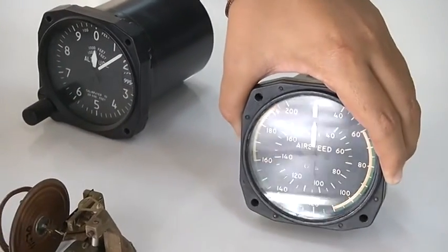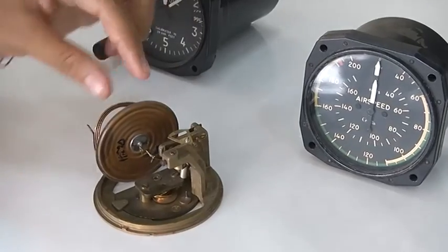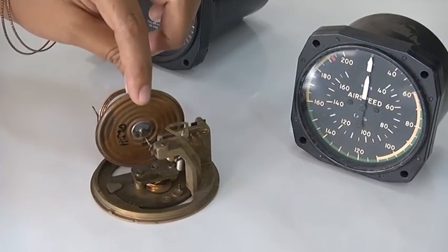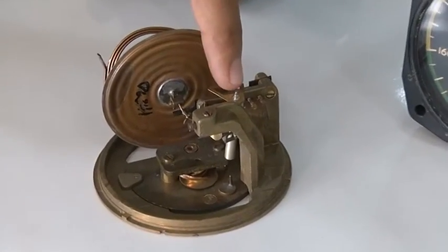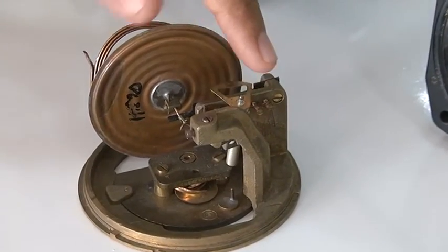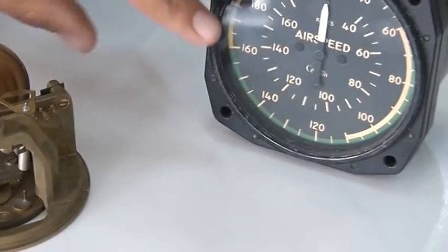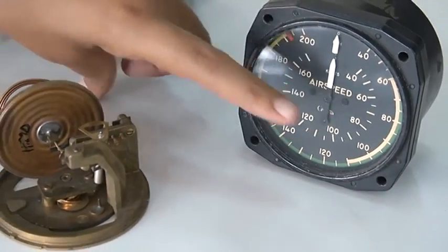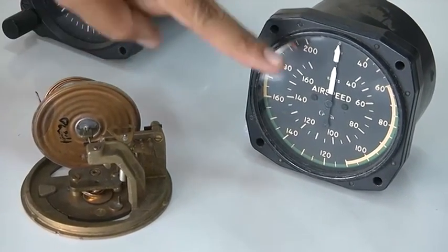Through this the air pressure goes inside and the difference of pressure is measured through this diaphragm by expanding or retracting it. Then through the coupling element, that is the gears and mechanical linkages, the reading is given to the indicating element on the gauges. Airspeed gauges are calibrated in knots. The difference of pressure when the diaphragm moves is shown on this gauge.